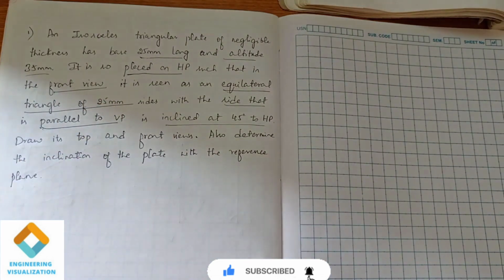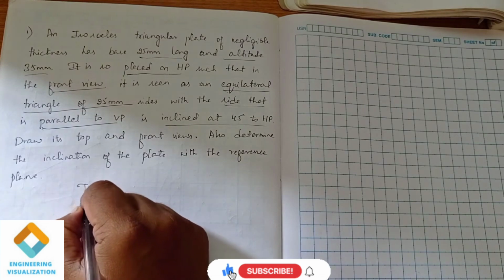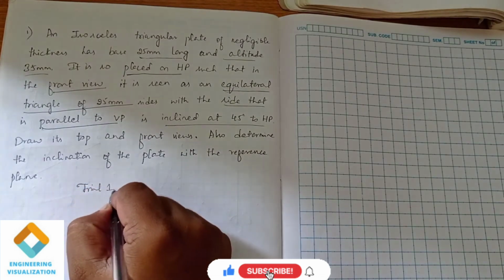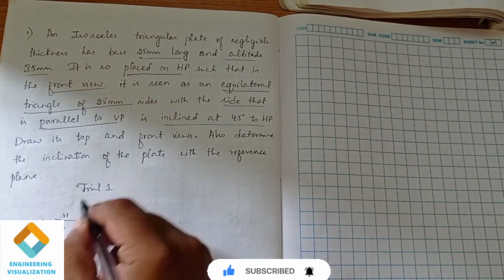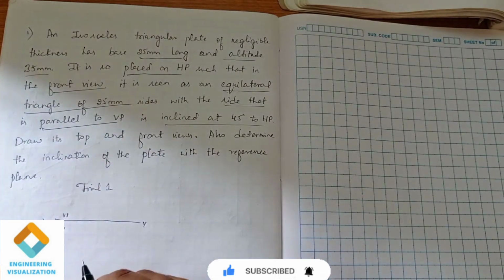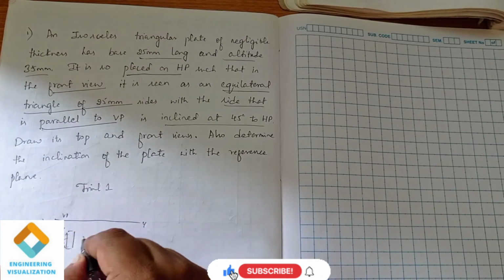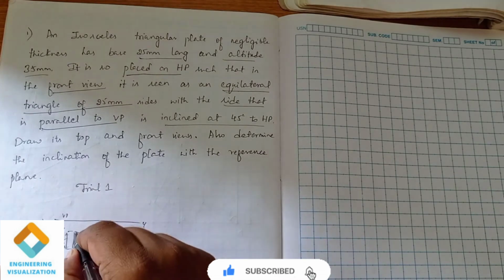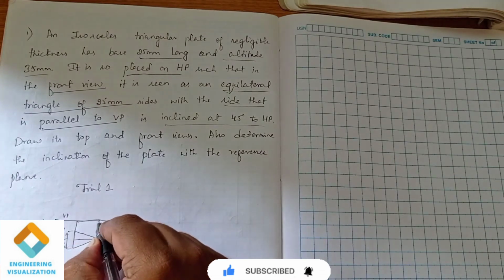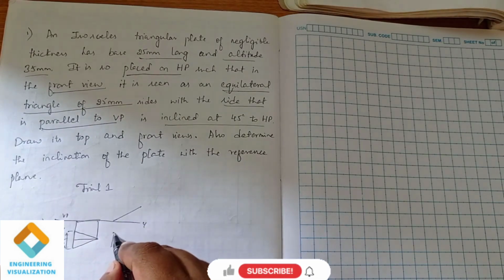So before going to the problem, first we have to identify whether it is resting on the HP plane or on the VP plane. For that I'll be doing a trial. In trial 1, say this is our XY, VP, HP. If we place it on the HP plane, what happens? Say this is our isosceles triangle. Consider this is the altitude. This is the top view, and this is the front view. Now by inclining this, we'll get an equilateral triangle here.